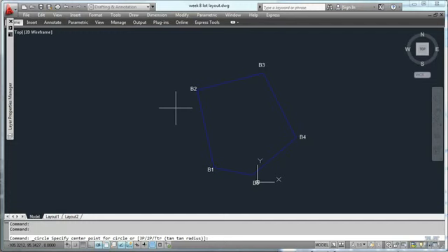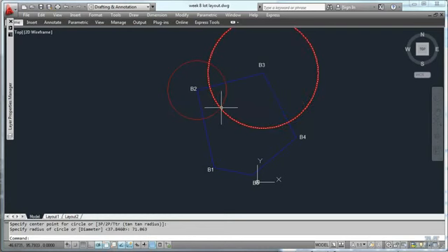of the building were. So for example, the northwest corner of the building is 37.846 feet from B2. So let's start our circle and just type in 37.846. So we've got a circle there, and it's also from B3 it's 71. So let's just draw the circle tool again. And that one is 71.063 feet. So right where those two cross is where the one corner of the building is.